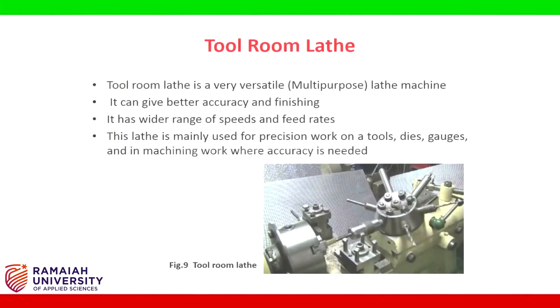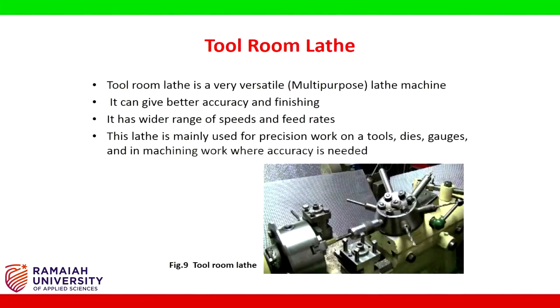Tool room lathe. Tool room lathe is a very versatile lathe machine. It can give better accuracy and finishing. It has a wider range of speeds and feed rates. This lathe is mainly used for precision work on tools, dies, gauges, and in machining work where accuracy is needed.